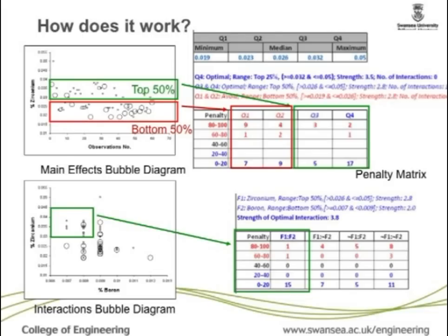We're not interested in statistical interactions, which you see in statistical packages. We're not interested in that, this is good because this is the p-value. We will just want to visualize data, because it's your own data. Visualize that data, cross-check with published literature, and then do confirmation trials. So even if, once you see this with very few observations, you get a trend, which way to move. And that is how you start tweaking your process.